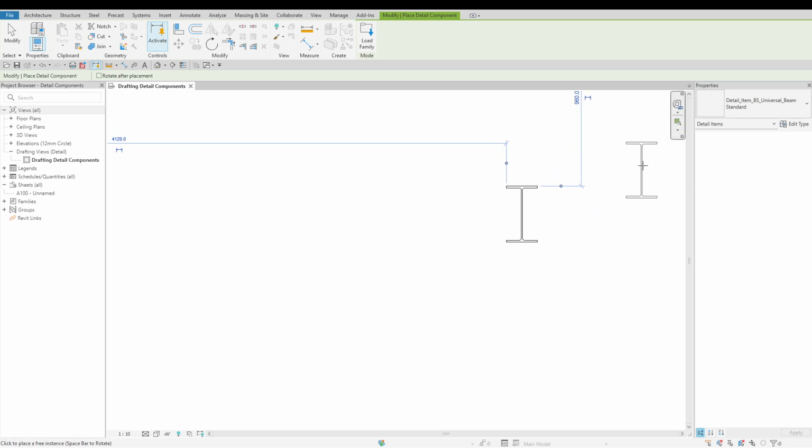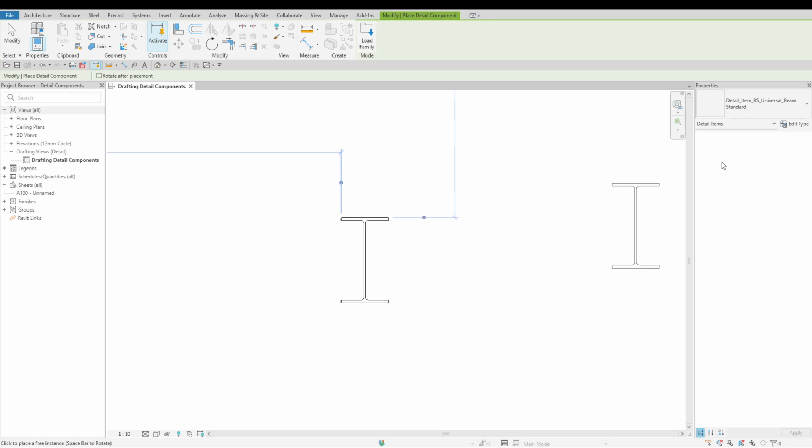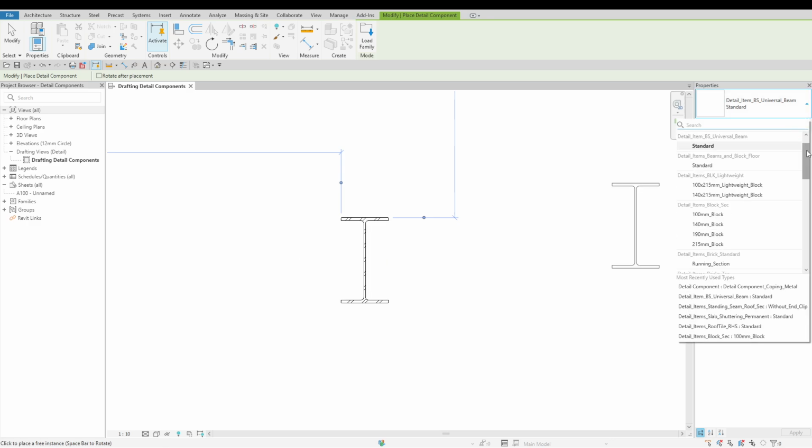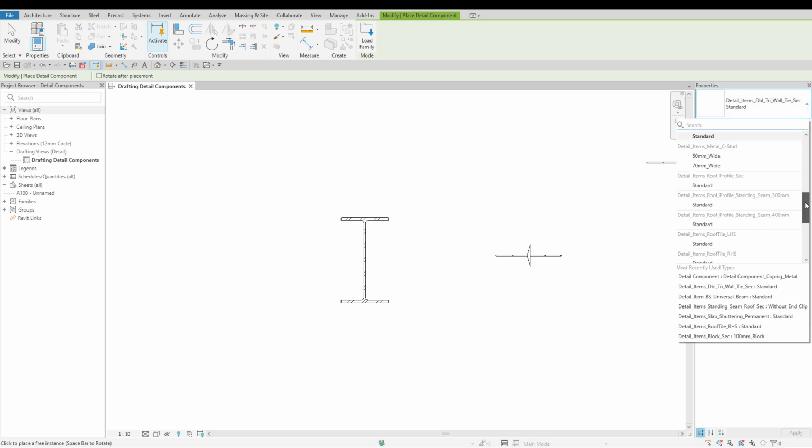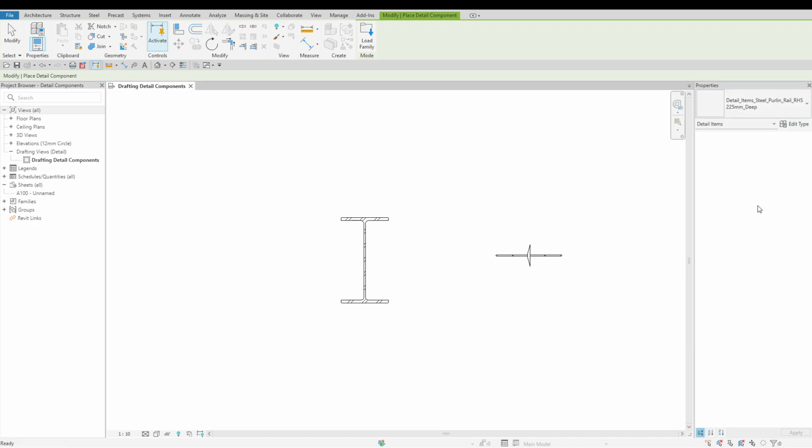While Revit provides a substantial library of pre-designed detail components, such as metal profiles and masonry joints, these should be considered as general representations. For construction-accurate detailing, including precise profile sections and exact dimensional specifications, it is essential to reference technical documentation supplied by material manufacturers and product vendors.